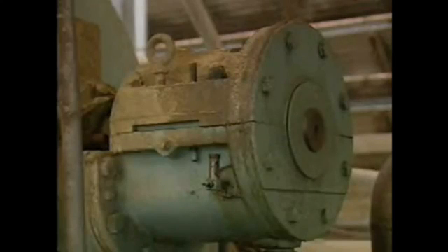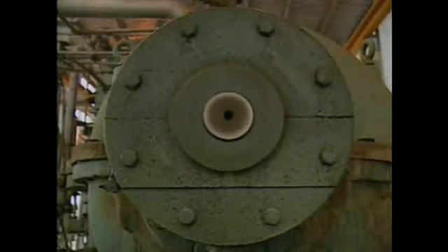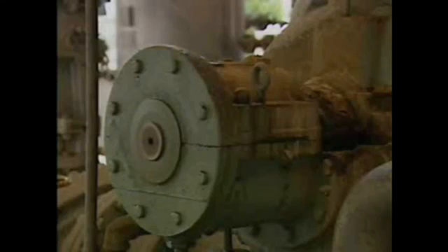Fatigue failure is caused by metal fatigue. When a bearing is in operation, it is continually flexing or bending. Although the amount that a bearing bends is very small, it is significant because it is continuous. There is a limit to the amount of bending and flexing the bearing metal can tolerate. After the metal has reached its limit, the bearing fails.